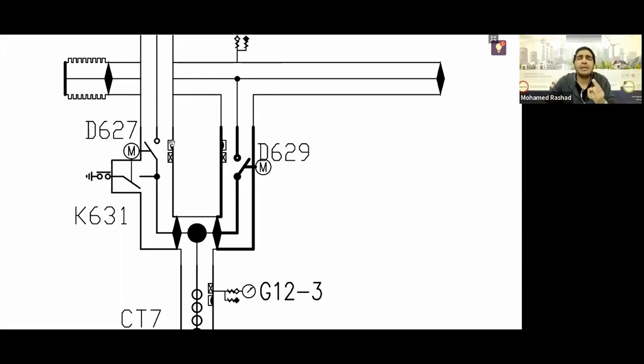For example, if the body can withstand a pressure of 10 bar or 20 bar, this part can withstand a pressure of, for example, 8 bar, or if the body itself can withstand 20, it can handle 15 or 16. So if the pressure reaches 15, the body can still withstand it. But this part is a weak point in the GIS body, so it is the one that fails, allowing the SF6 gas to escape outside. Thus, I have preserved my GIS body, and I can later come and replace my ruptured disc.